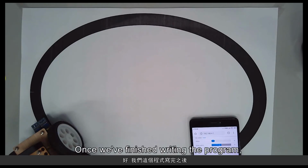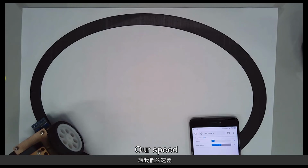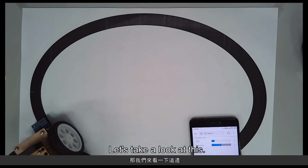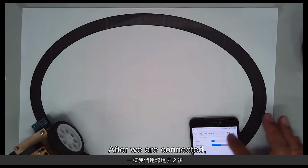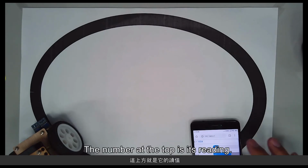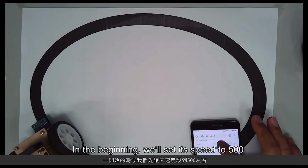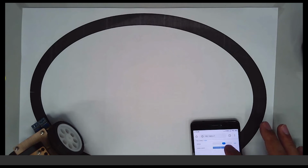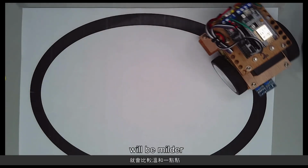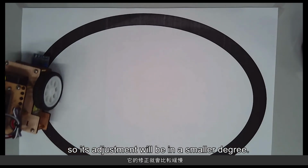Once we have finished writing the program, we'll use the map function to correct the past margin of error. Our speed will be adjusted according to the error value. Let's take a look at this. After we are connected, we can measure its reading. The number at the top is its reading. We can set out its rotational speed. In the beginning, we'll set its speed to 500 and start it up. You can see that its swaying will be milder because the error value is not too big. So its adjustment will be in a smaller degree.